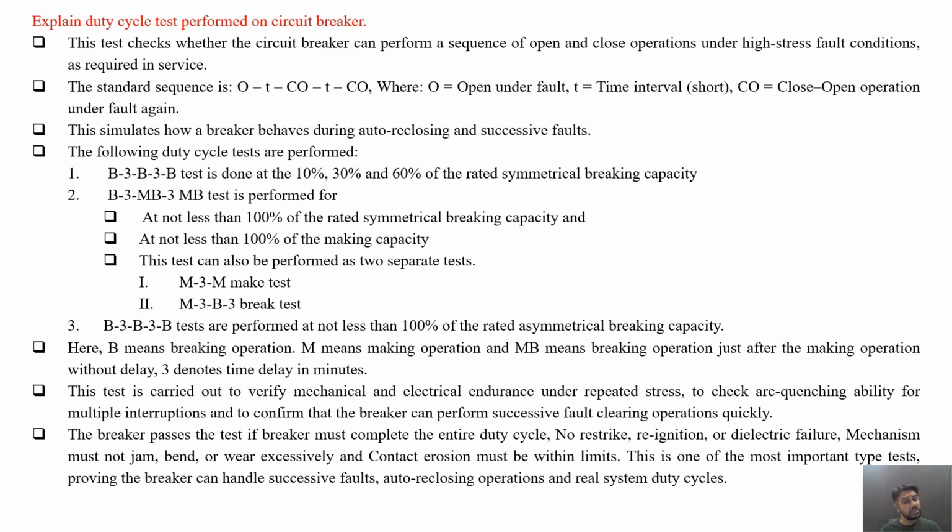This is one of the most important type tests, proving the breaker can handle successive faults, auto reclosing operations, and real-time system duty cycles under fault conditions. So this is all about the duty cycle test performed on circuit breaker.